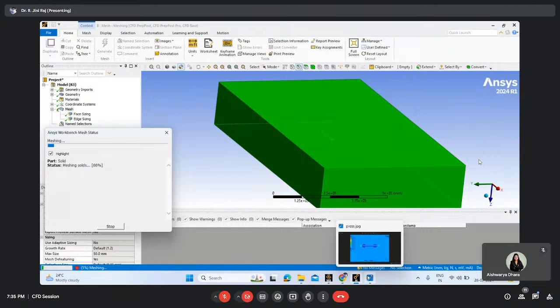And one more thing: you can find some bodies where meshing is not happening and more errors are coming. Then you can straight away consider that we need to clean the body first, then only it will mesh. You can go with the automatic mesh initially and check what problems are occurring, and after that you can finalize which regions need to be rectified or cleaned before bringing to mesh.